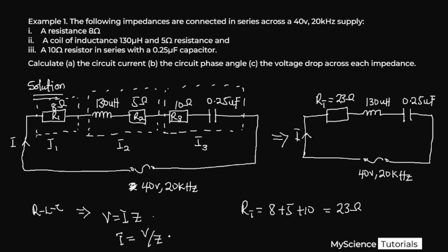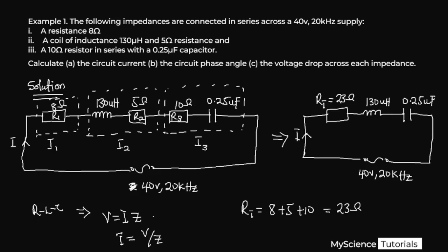So let's go ahead and do that. Now the formula for finding impedance is the root of resistance squared, which in our case will be RT squared, plus the bracket XC minus XL, squared. This means that we already have our resistance, or R total. We already have that, so we are good to go. But we do not know XC, and we do not know XL.